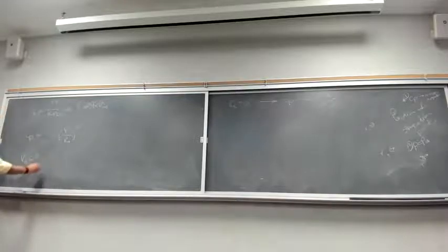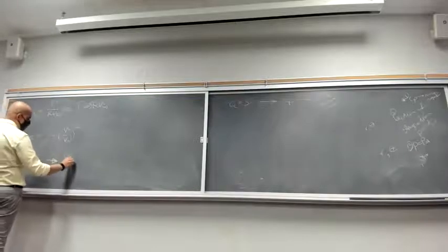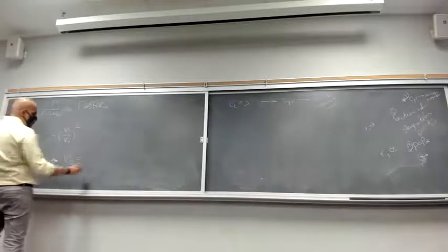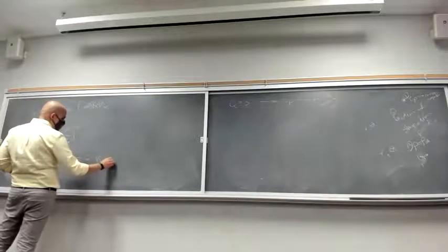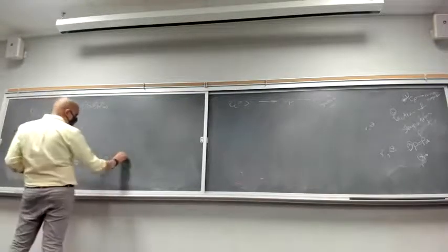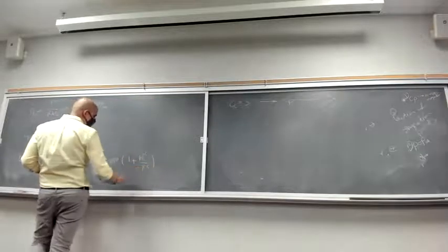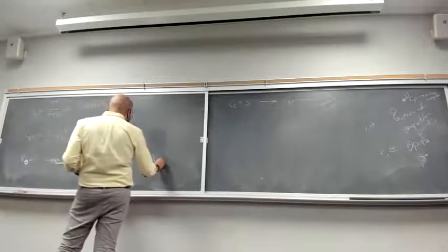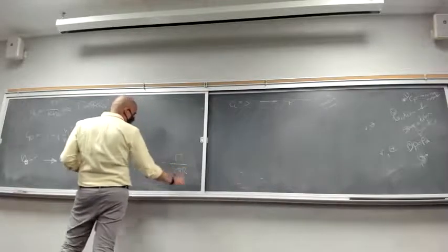It is on the surface, so we only have V theta, right? What was the formula for V theta? It was negative V infinity. I don't remember the formula. Sine of theta times 1 plus R squared over r squared, right? Minus gamma over 2 pi R, right?